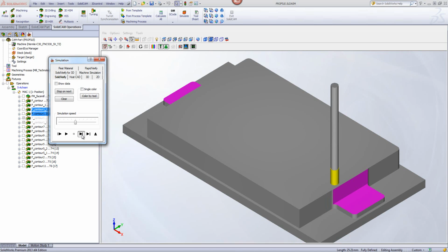Now, when it gets to the wall, it's going to go up, and now it's going to clean the floor with the wall itself every 5 millimeters. That's what the 5 millimeters is for, the step down, where the finish cut does a 5 millimeter step down.